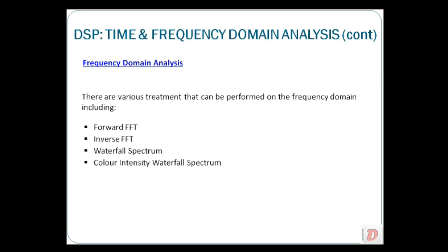which is also similar to the cascade spectrum. The cascade spectrum is plotted over speeds, the change of speed. If the speed changes, you plot an FFT. Another speed change, you plot another FFT. It is usually used when the machine starts up from 0 to its running speed, its running frequency. So when it starts up from 0 to let's say 100 hertz, maybe every 1 hertz you plot its spectrum, its FFT.